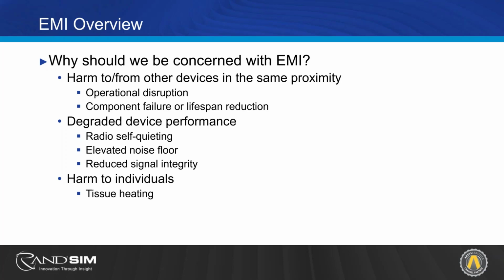And then on the floor above, you have some construction going on and they're using some power tools. As I mentioned before, fluctuations in current and voltage are going to induce some sort of emission. In that example, it's going to be a conducted emission, and that can couple back down onto the power lines. If EMC and EMI mitigation hasn't been taken into account, that energy could couple into that medical device, causing an operational disruption, which would be very problematic.